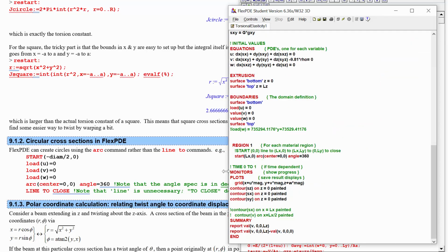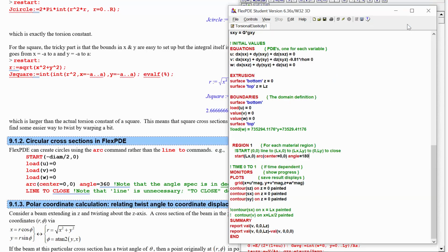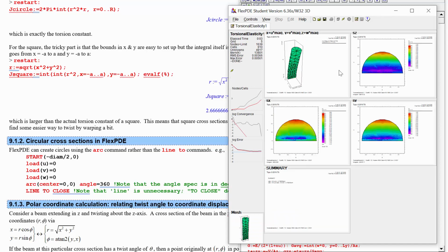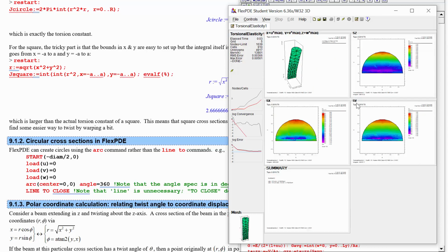and draw that circle. You don't have to do a 360-degree arc. You could do a 180-degree arc. This is going to show us whether it draws in the counterclockwise direction or the clockwise direction. Let's find out. Let's edit. We made a mistake. We have to, after that arc, go line to close it off. All right, so it looks like it draws in the counterclockwise direction first, because we have just the top part of this, and then line to close.